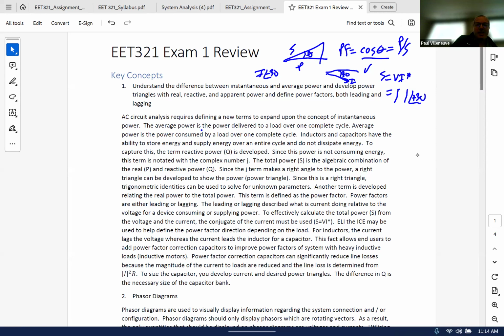And we did a bunch of examples, and I think there was one homework problem where we actually sized a capacitor bank. You can size them in ohms, but ultimately we size things in farads because that's what you buy or build. So you get the idea.